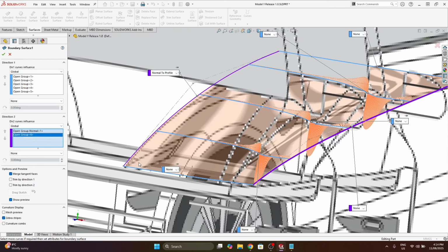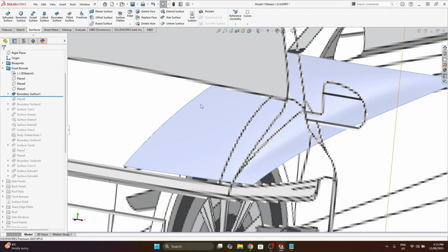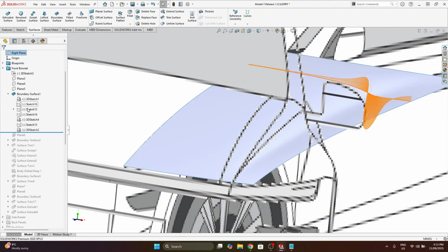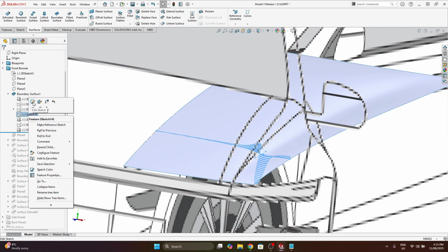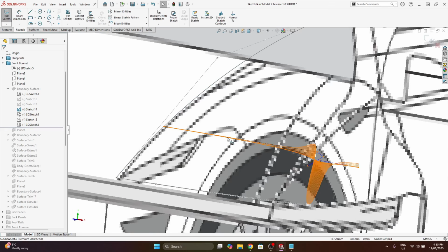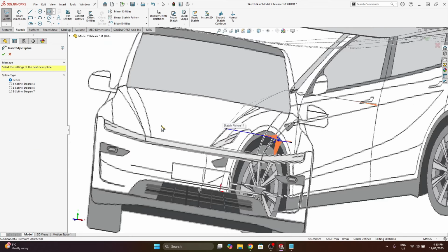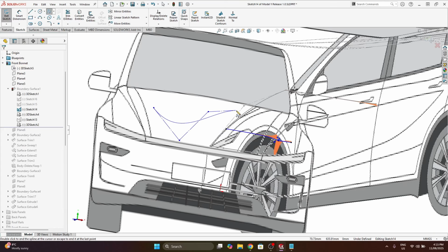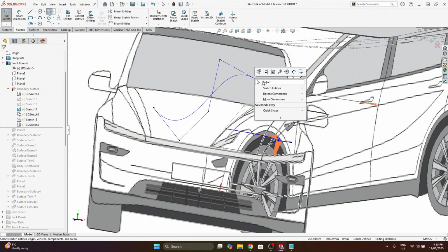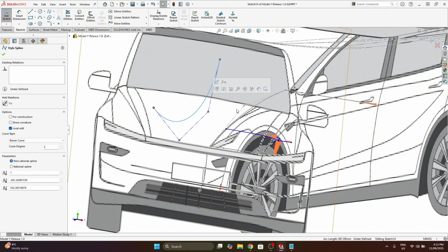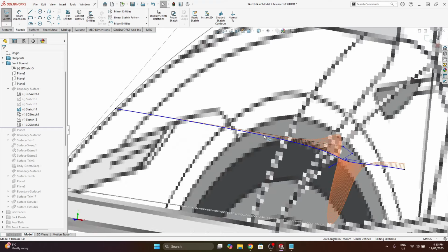Another important thing is each of these guide curves. So actually just going into one of these guide curves, it's quite important. I use style splines, which generally you want to use over regular splines. You just get a lot more control. With style splines, you draw your CVs, your control points, to draw up the spline. Now this style spline, for example,